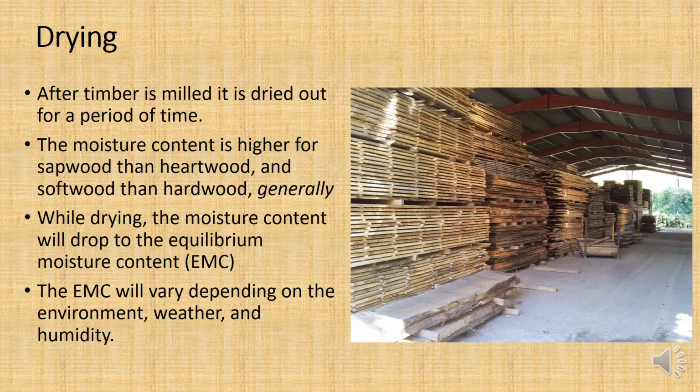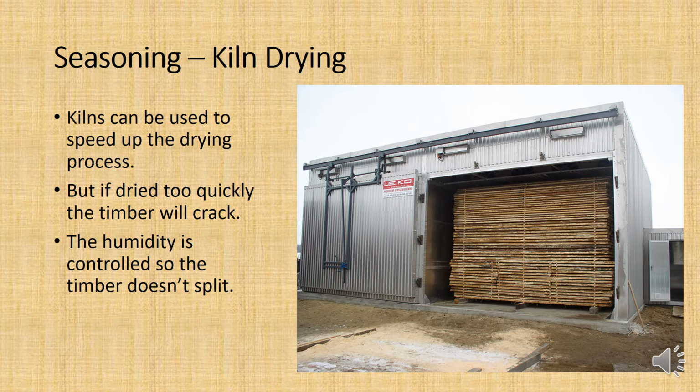So this is something that a lot of people, particularly in the Middle East where you don't have a lot of wood, don't actually realize. You can't just use wood straight from a tree. You've got to dry it out, and that drying process can take a long time. So when we are drying the wood, the timber, this is actually called seasoning, if you like.